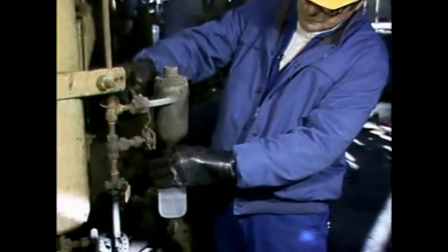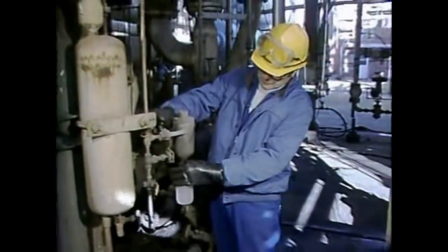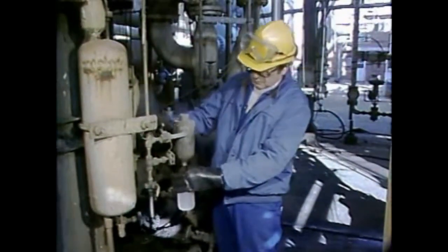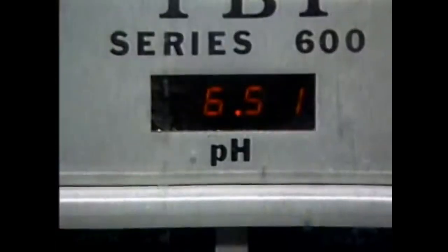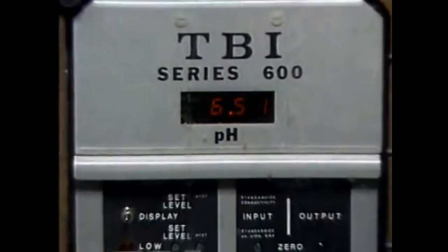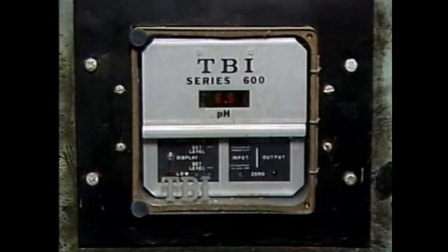One way to check for contamination is to take a sample of the lower pressure fluid and test it for the presence of the higher pressure fluid. In some cases, contamination in the sample can be seen. In addition to sample test results, conductivity and pH readings of cooling water may indicate a tube leak. If there is any indication of contamination, it's important to determine the source of the problem and take the appropriate corrective action.